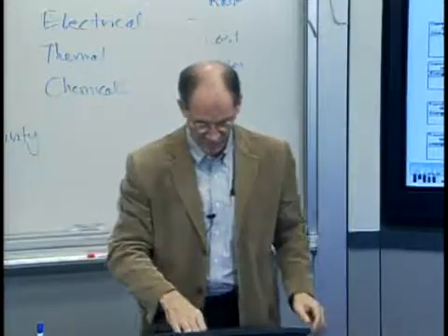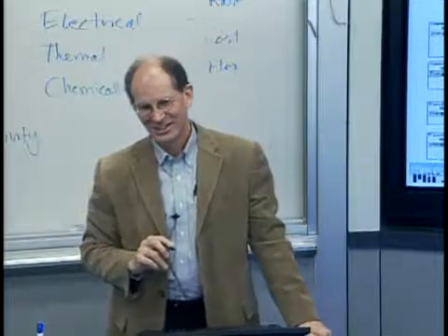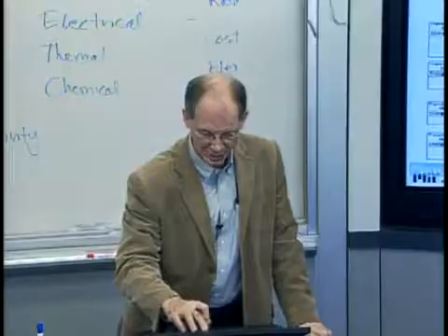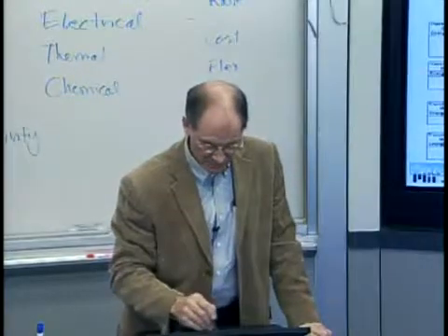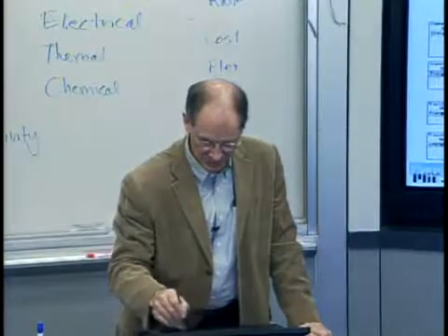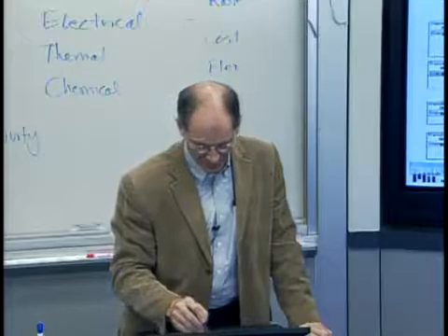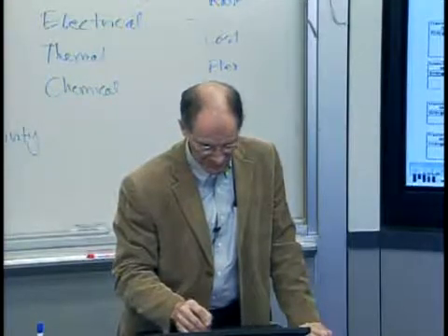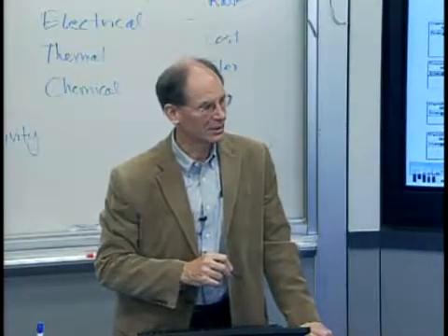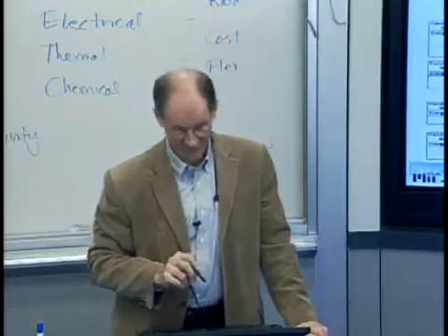So I guess my point is, and now it's getting a little bit dated, but when these rapid prototyping processes were all the rage, it was interesting to notice that on this taxonomy, some people realized, and it's been done for a lot of different things, that I can take a parallel process, and if I serialize it, it all of a sudden becomes a rapid freeform method, doesn't need any tooling.